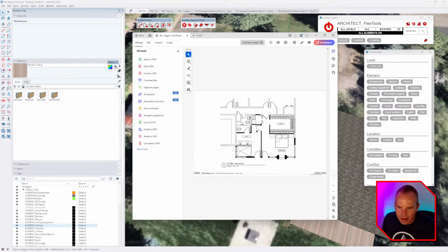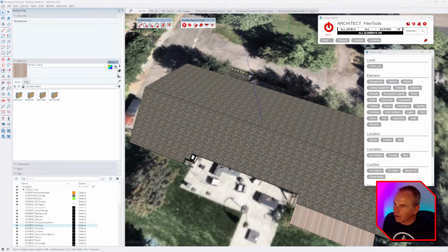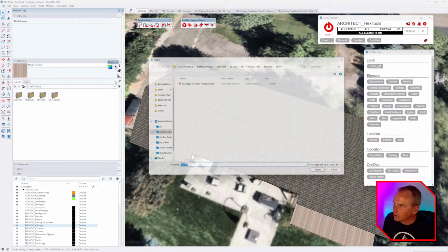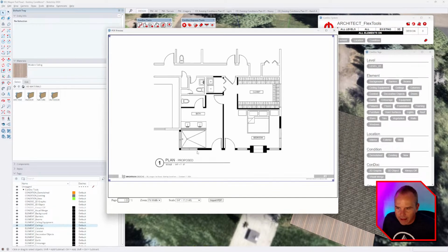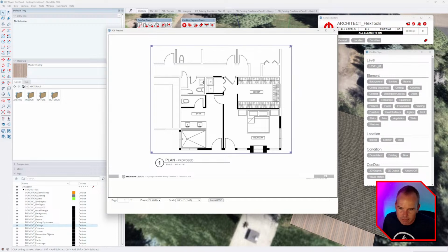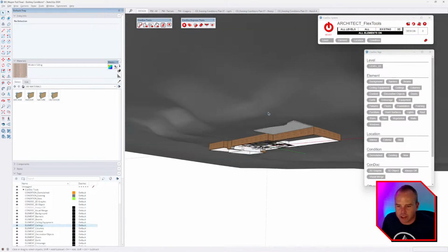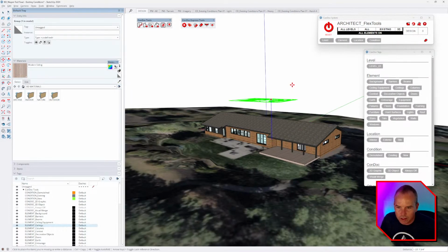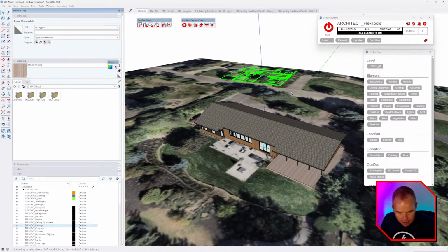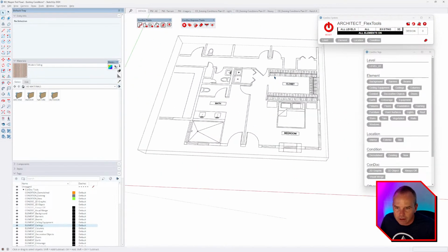Here's that without the dashed lines, and then we'll go to File, Import, and pull that in. Same drill here, looks pretty decent to me. 1/4 inch, import PDF, and that's going to show up right on the bottom there. Then we'll use the move tool and jump in there and take a look. See, now we've got this nice, clean proposed conditions CAD file.